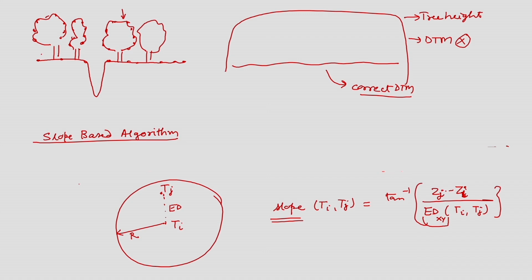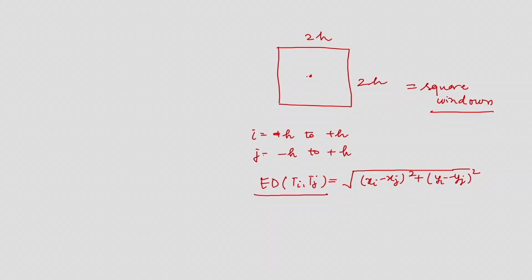We can see that we have written these algorithms for DTM extraction using the vector data. I can also write these things in raster. These are the methods which are generally used for digital terrain model development.